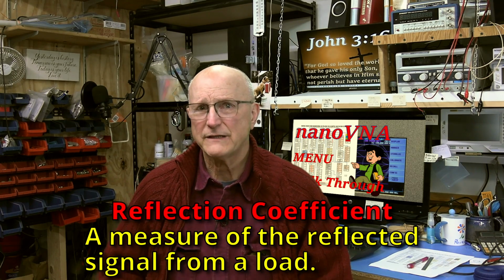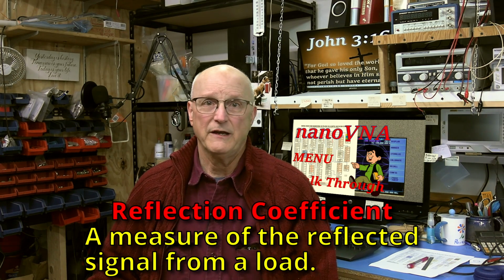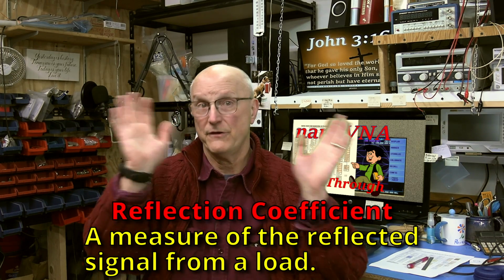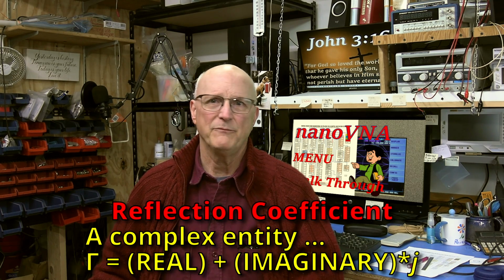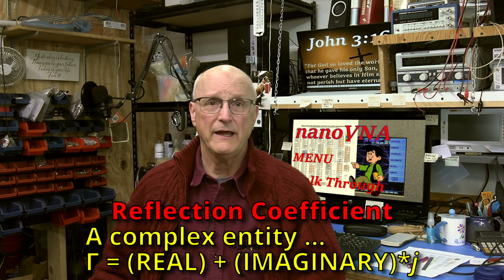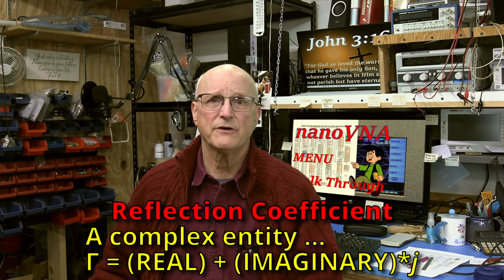Well, so much of what the display formats are all about is centered around what is called the reflection coefficient. So, if you're going to have some understanding of what these things are, I need to spend just a moment explaining what this is. First, all of the reflective measurements that the VNA does start with the reflection coefficient. This is what the VNA measures and then mathematically calculates everything else from that. The reflection coefficient is a complex entity. That means that it is comprised of both a real and imaginary part, just like impedance. It is represented by the uppercase Greek letter gamma.